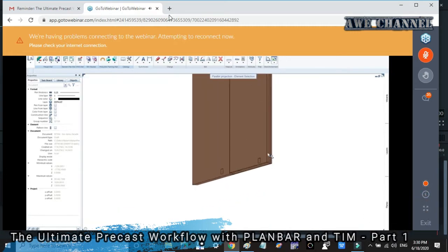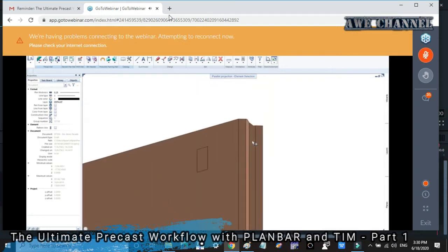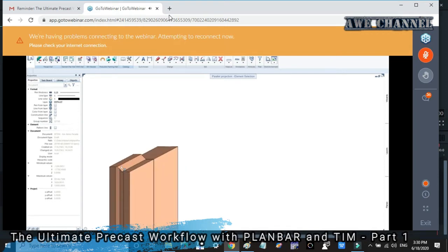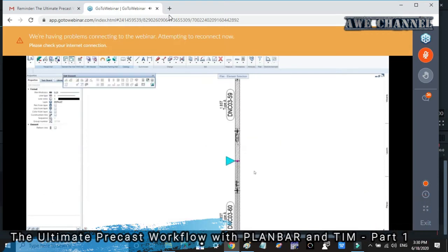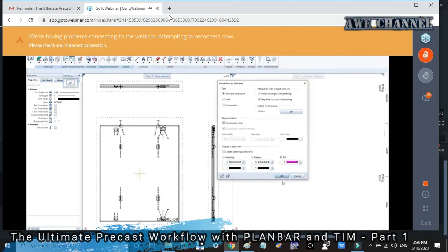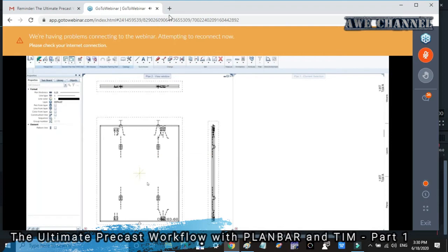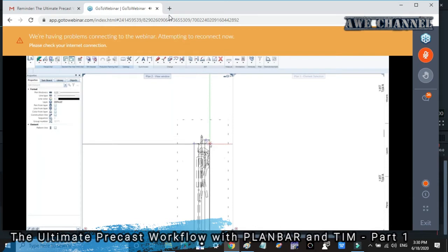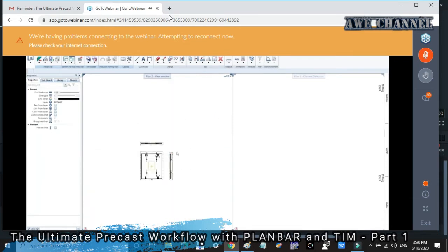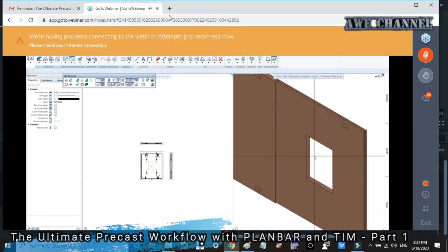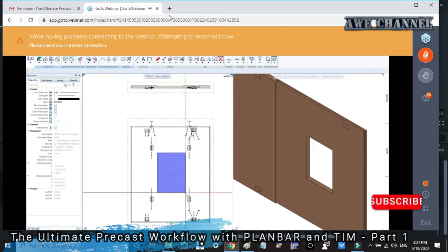This is the horizontal connection for your facade wall element at the bottom, and this is the horizontal connection for your top facade elements. In case you want to make some opening, we also have the possibility to do it by using cutout. You just use negative and then define the size of your opening and the depth of it. And right now you have the opening, and at any time you can delete it if you don't want to have it.